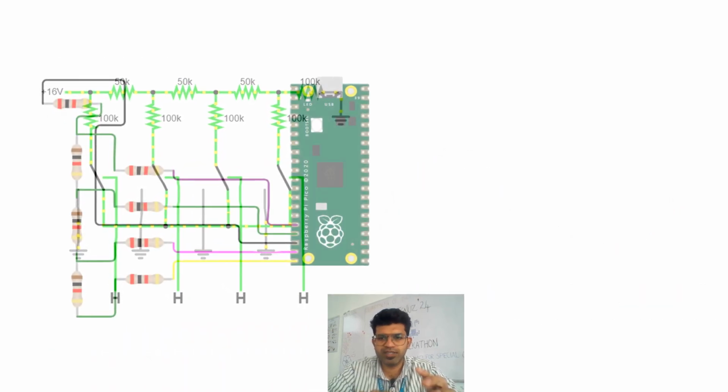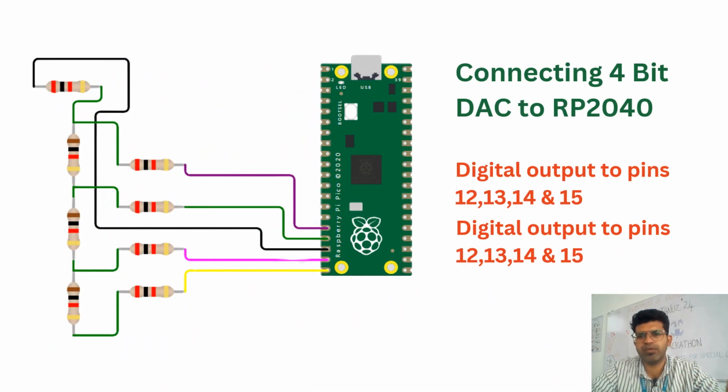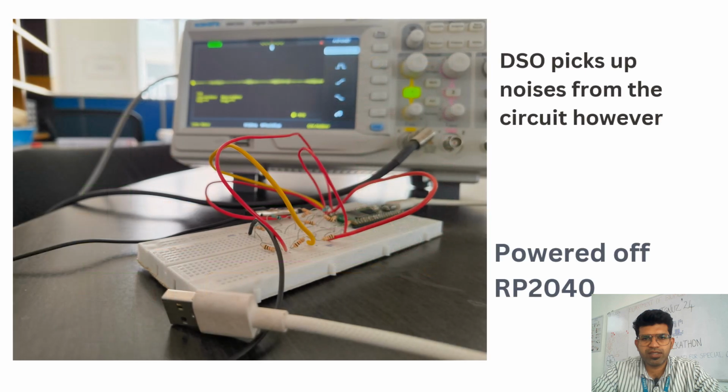And this is how I'm going to connect. The connection is going to be with the Raspberry Pi Pico through the resistors. Here the power voltage will be from the digital pins themselves, and one particular part is grounded, which is something we saw in the previous slide, the configuration. And this is how we actually implemented it.